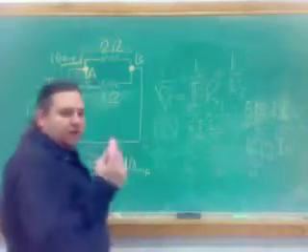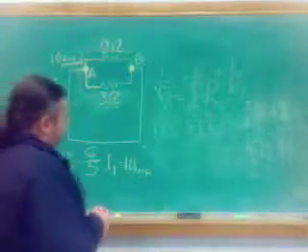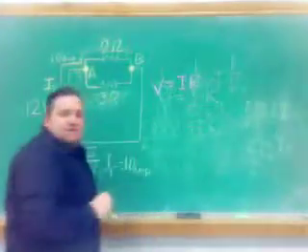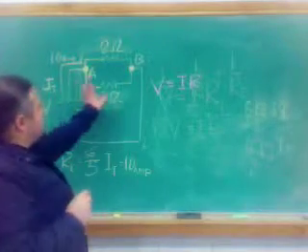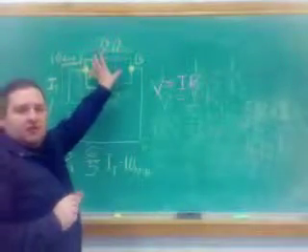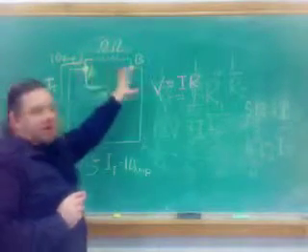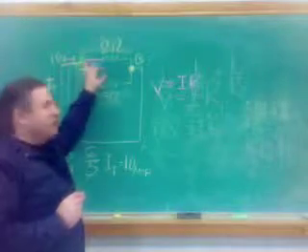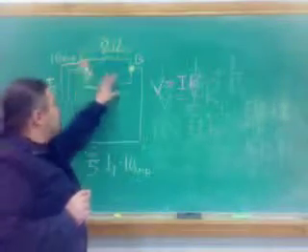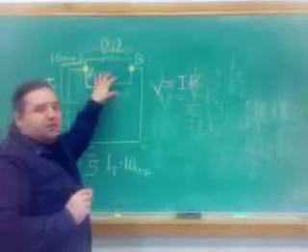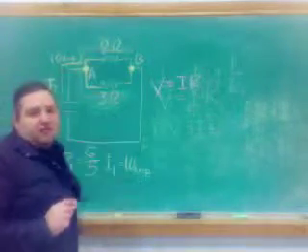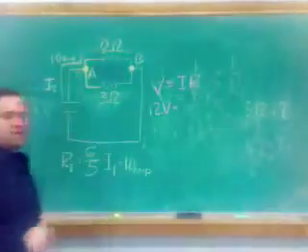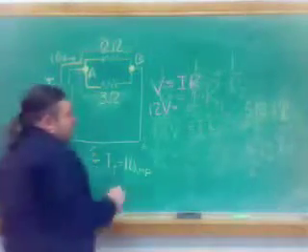Okay? So, I'm going to use red now. I get V is equal to IR. Okay? Voltage across each one of these resistors, it's still the 12 volts. All of it has to be consumed, and these two resistors are going to consume it. So the potential drop from here to here is 12 volts. So that's how much potential drop that resistor experiences and that resistor experiences. So I get 12 volts is equal to the current, which I don't know, times the resistance.